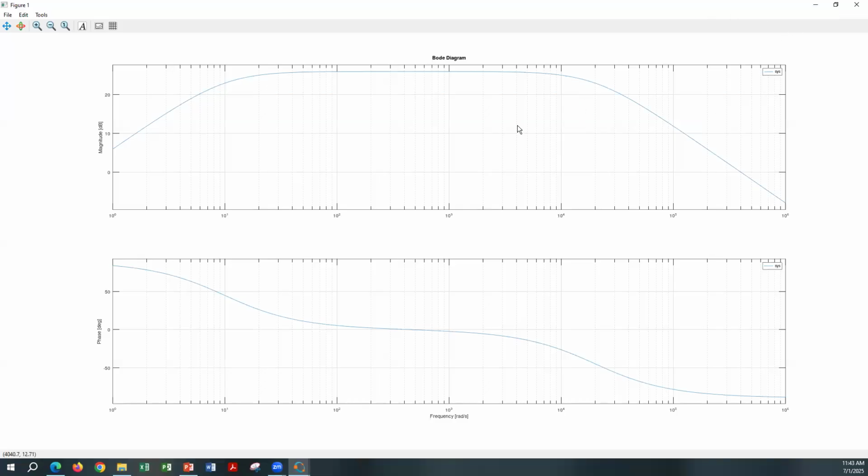So again, this is the decibel plot. It looks similar to what we plotted, but this is the exact plot, not the approximate. Bode is an approximate plot because you can see these curves are so smooth. For the Bode approximation, the curves are never smooth because it stays flat until the cutoff frequency, and then it starts dropping or rising.